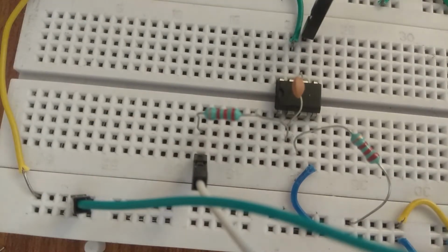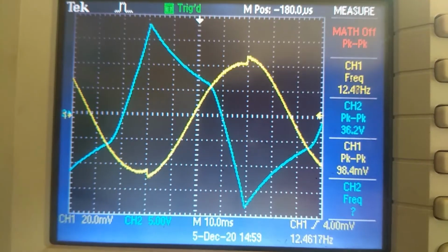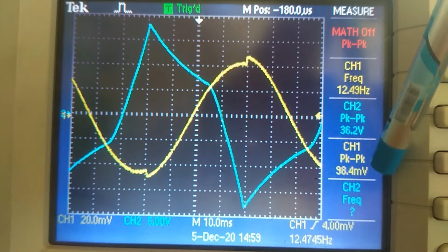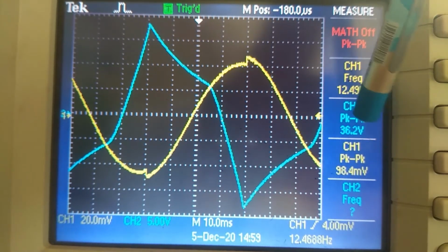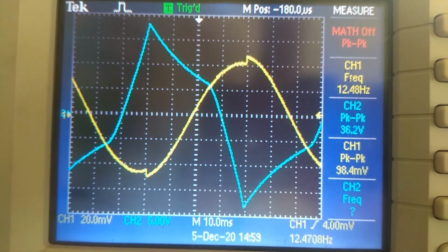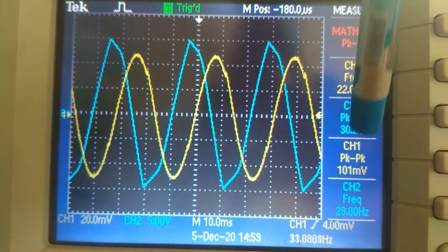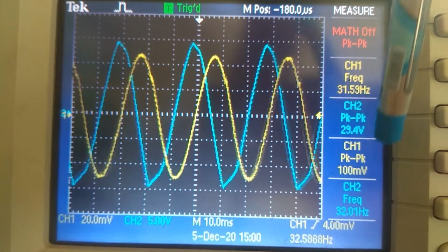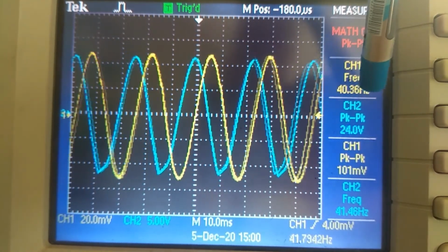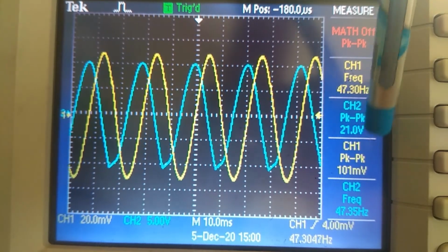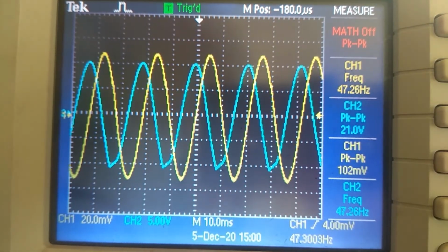Now let us zoom on the DSO. Let me show at lower input, this input that we have applied around 100 millivolt, and the output we are getting is just a saturated value. Now when I increase the frequency, see there is fluctuation, that's why I am starting from 50 hertz. After 50 hertz there will be much fluctuation in the input. See, our output came to 21 volt.